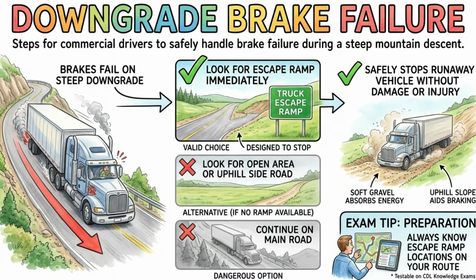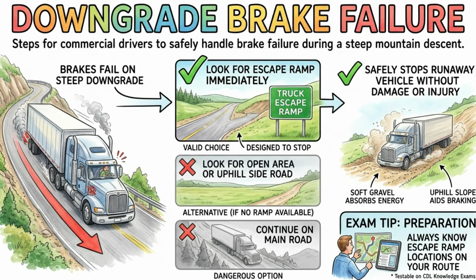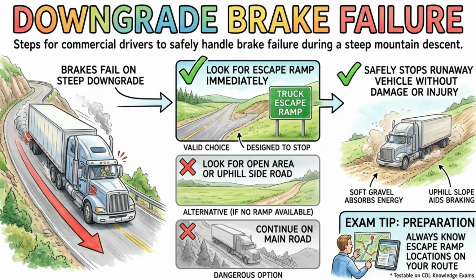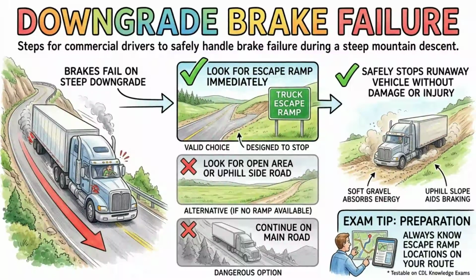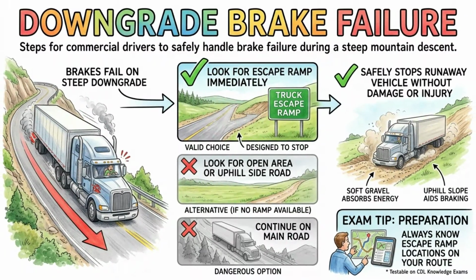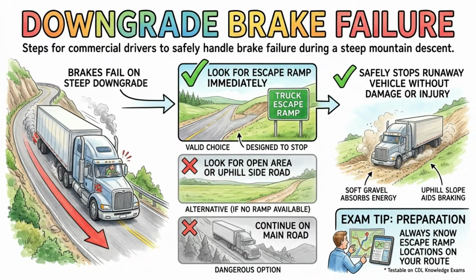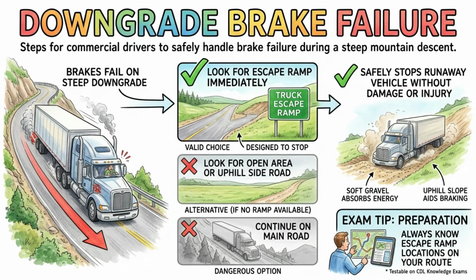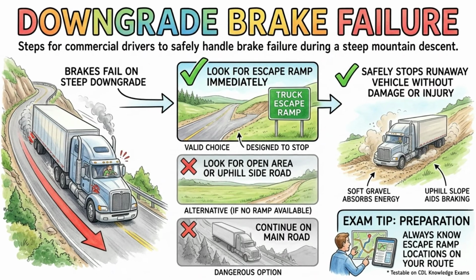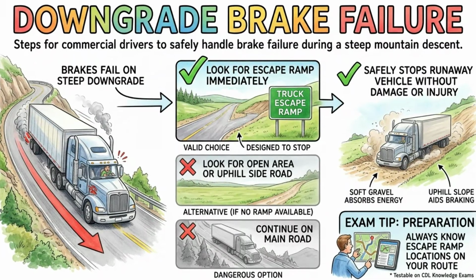Just as you watch the space above, you must also monitor the space below your commercial vehicle. While trucks sit high off the ground, they can still be easily damaged by large debris, deep potholes, or uneven railroad crossings. If you try to drive a heavily loaded trailer over a severely raised railroad track, the belly of your trailer can actually get stuck on the tracks. This is called hanging up your trailer, and it is an incredibly dangerous situation that examiners will expect you to know how to avoid.